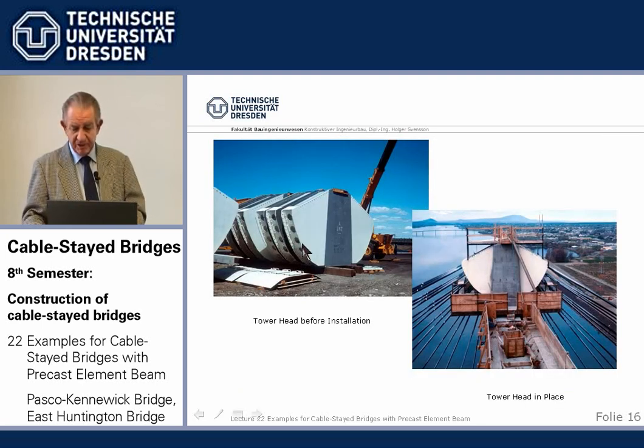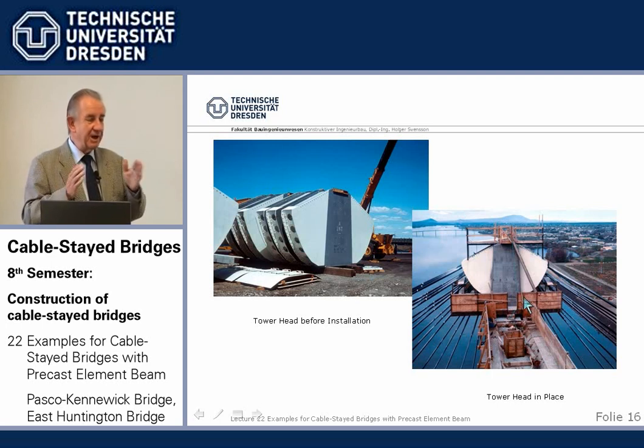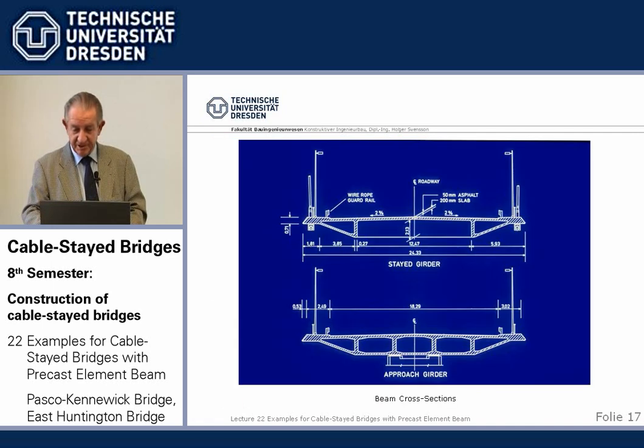The tower, as I say, we had 3 stay cables, one beside the other, and they were delivered in 3 slices, I may say, pieces, lifted up by crane, installed. The cables here are already in, and then the concrete tower was continued up around these steel boxes. We used to call them concrete ears, where the steel part is our head and the concrete ears, a little bit bigger, make it composite with the tower.